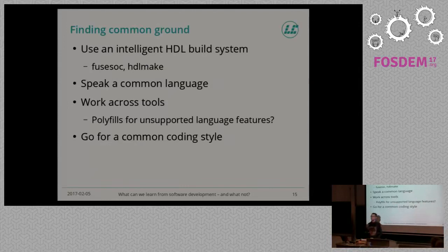So isn't there something that we can do? For example, SystemVerilog has nice features, but if you look at the tool support, it's just not there, because every tool has a lot of different parsers for SystemVerilog. Vivado has 2 different parsers that parse SystemVerilog, so you can use one construct that works in simulation but not in synthesis. That's just annoying, and this won't get any better anytime soon. So can't we have a source-to-source compiler that says we go to the common denominator and go from there?